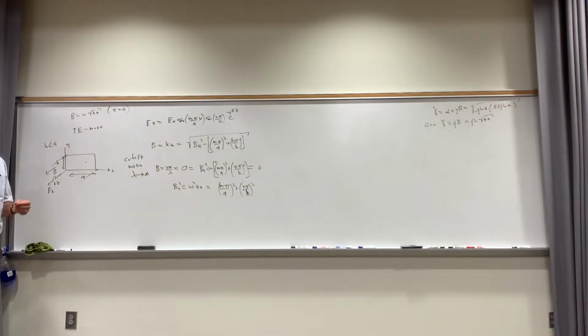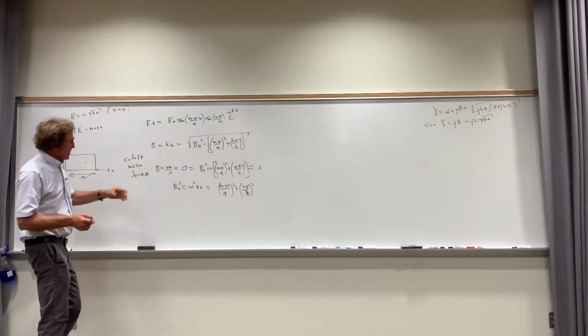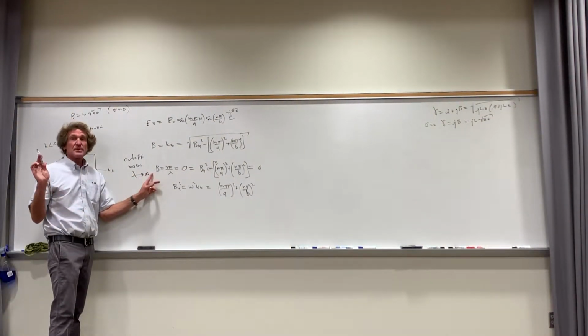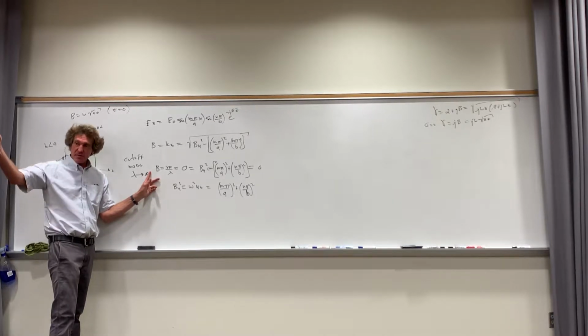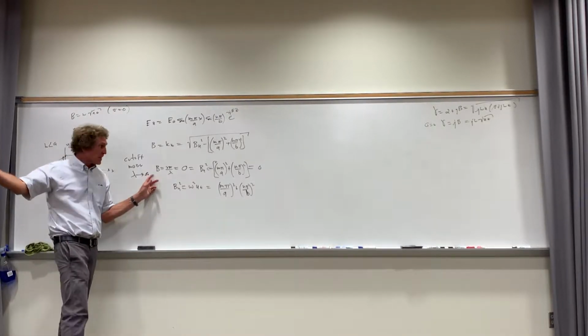Well, actually, it came from the development of the wave equation, the Helmholtz equation, the del squared of E plus beta squared E equals 0 thing. Remember that? If you don't remember clearly, it was in chapter 6 we did this. So now, listen to me here, because I want to make some points. Here is the cutoff mode. The frequency associated with that is the smallest frequency that will allow propagation down that pipe, down a rectangular waveguide.